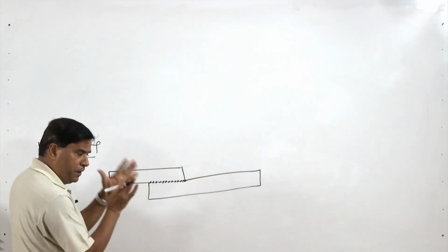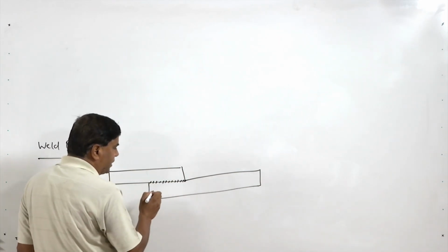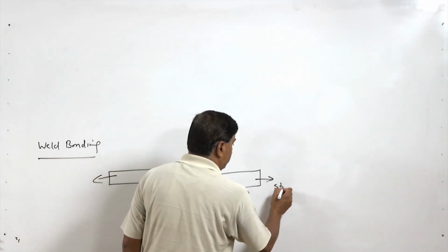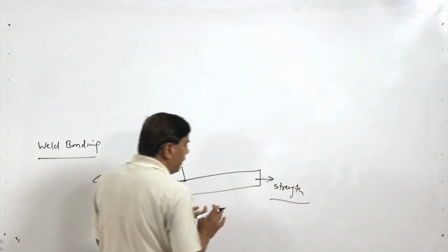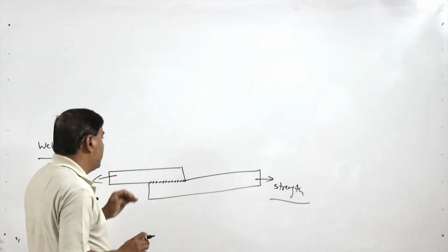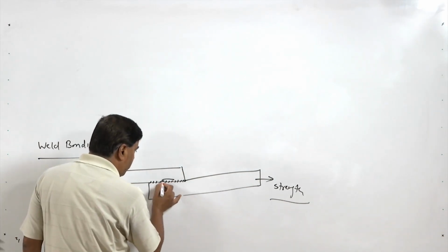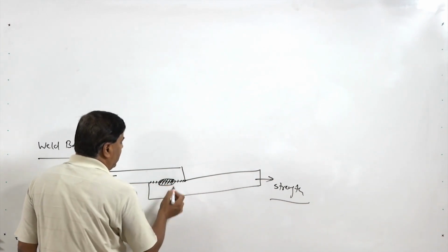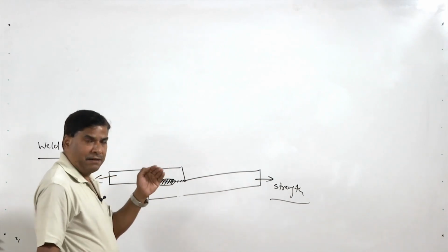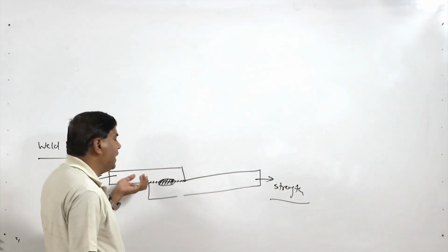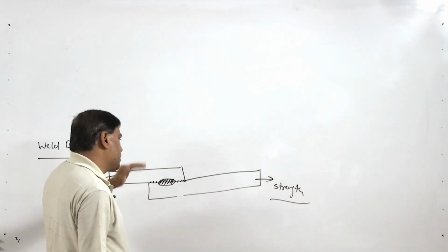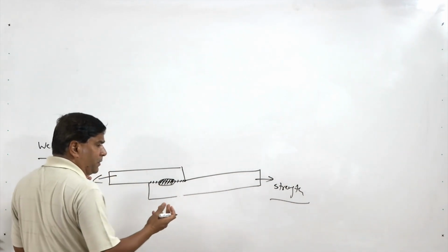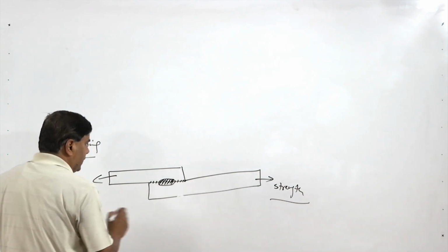This adhesive holds the plates together and provides some shear strength to the joint, which is further reinforced or enhanced with the spot weld nugget. When the spot weld nugget is developed, it develops the metallic connection or metallurgical continuity, while earlier there was just an adhesive connection. So, this spot weld further increases the load carrying capacity of the joint.